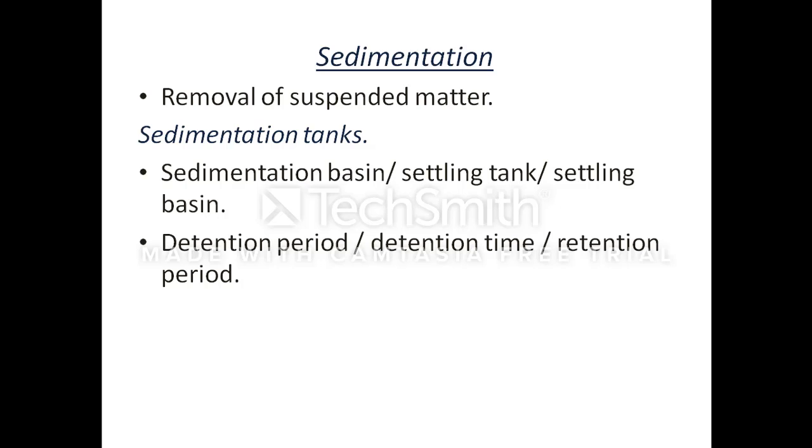If the water remains still or at rest for some time, the particles settle down at the bottom. The same principle is used by the sedimentation tanks. What's a sedimentation tank? It is a tank which holds water at rest for some time until the particles settle down at the bottom. So we can easily remove the suspended matter from water.